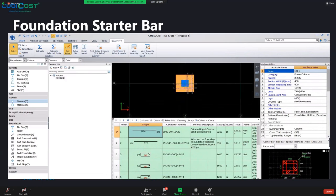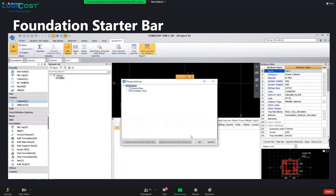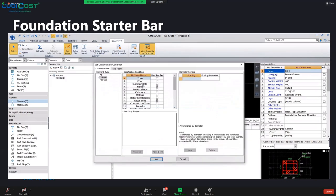So what about the quantity? How can I separate out my dowel bar quantity from my main bar? After you calculate the whole model, proceed to view quantity by category. Select the particular form, click OK. Select column. Select the set classification condition, because as you can see here, everything is lumped. If you want to separate out, you need to go to set classification condition, and then select rebar classification.